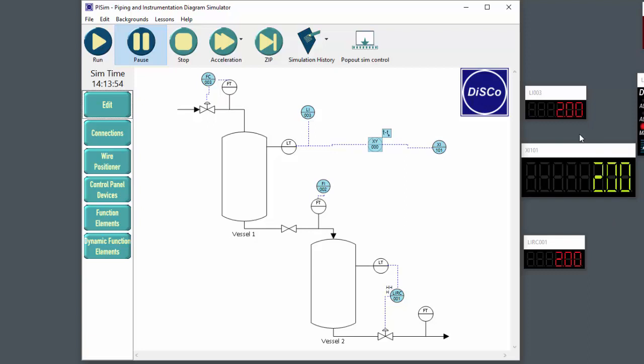Why would you want to implement the dead time in a control configuration? Well, you might need it if you're putting in a dynamic feed forward scheme, if the disturbance and manipulation signals have different delay times that they affect the output response. You might also want to use it if you're putting in dead time compensation into a control scheme as well.